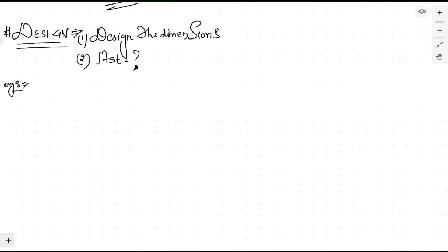In the question they are saying that you have to design a reinforced concrete beam for a load, लोड दिया हुआ है आपको, for a load of 50 kilonewton per meter. It means that the self weight is included under this. This is 50 kilonewton per meter, which is the UDL which is acting over the beam. The beam is simply supported and having a span of 8 meters. This is simply supported beam with a span of 8 meters.